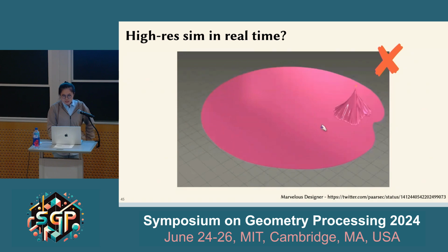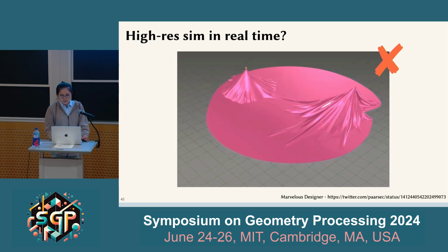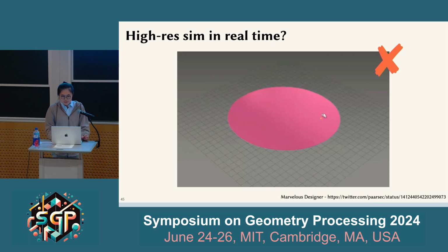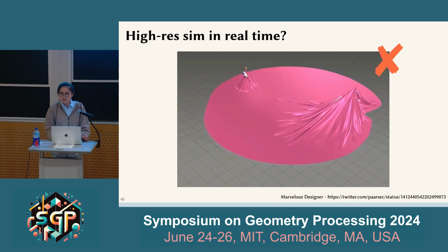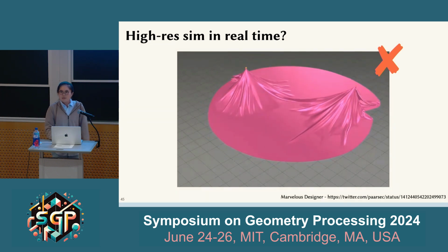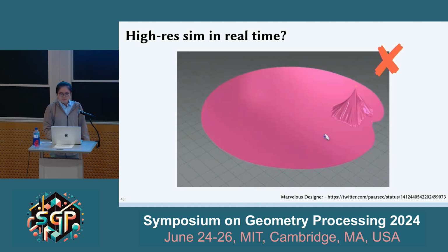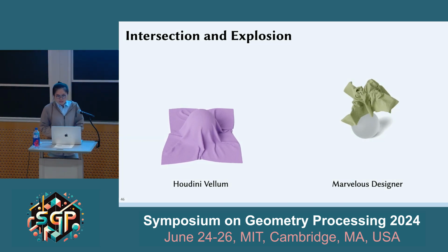And this is mainly because the high-speed methods for cloth simulation, for example, are now reaching interactive rates for extreme-scale cloth meshes. Due to the simplification and the limiting assumptions made in the simulation model, their expressiveness is still largely restricted. As an example, in fast complementary dynamics, using a subspace still reduces some amount of the wiggles and jiggles. And even worse, in some contact-rich scenarios, the simulator can be incredibly unstable and sometimes generates undesirable creasing and intersection artifacts too.